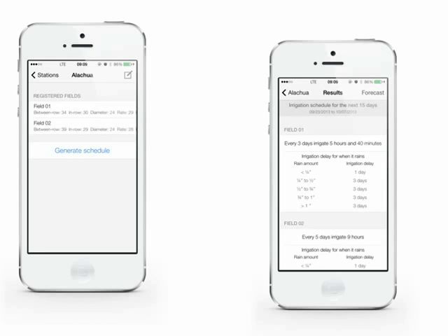If you have less than 1/4 of an inch of rainfall, you delay your irrigation by 1 day. So if you're in the middle of this 3-day irrigation interval and you get 1/4 of an inch of rain, you just irrigate 1 day later for the same amount of time.